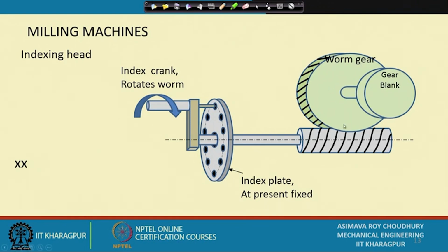We have already seen what a gear looks like, and we have already studied what a worm and worm gear is. So, let me just add here, this one is a worm and this one is a worm gear. And we have studied that they can provide us with drastic reductions in rotation. For example, if I am having say n rotations here, I might be able to get say n by 40 rotations. That is no problem at all. I can reduce the amount of rotation 40 times.